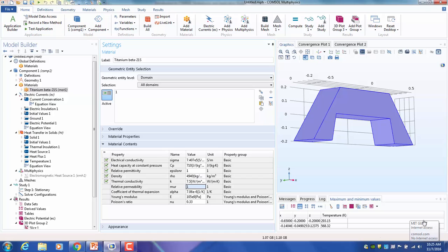So for example, if you have a fluid flow problem, what you care about is the velocity field and the pressure field. A typical mistake people make is they say what is the velocity input, what's the flow rate output, things like that, but they forget to give a pressure constraint. Then it's not a unique solution system. You could add any constant to the pressure of the entire system and it'll still be a solution. So in that case, COMSOL either cannot give you a converged solution or it'll give you an arbitrary solution.